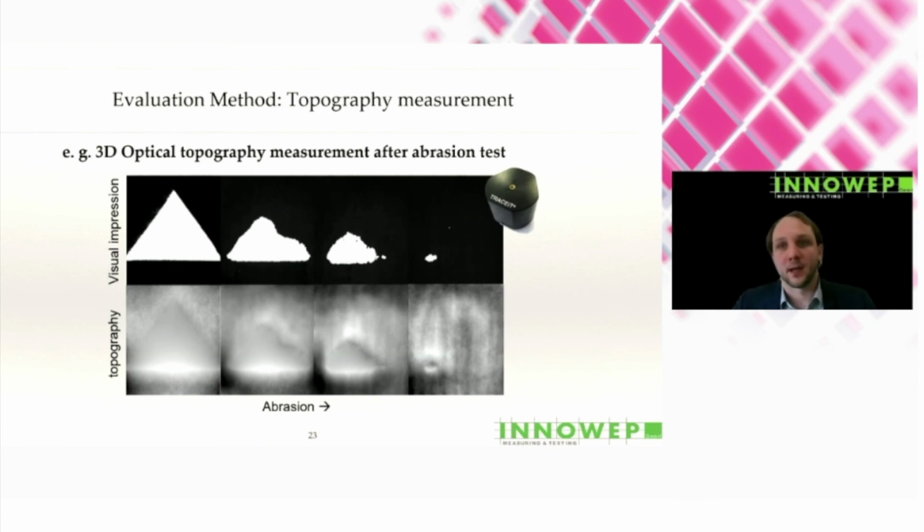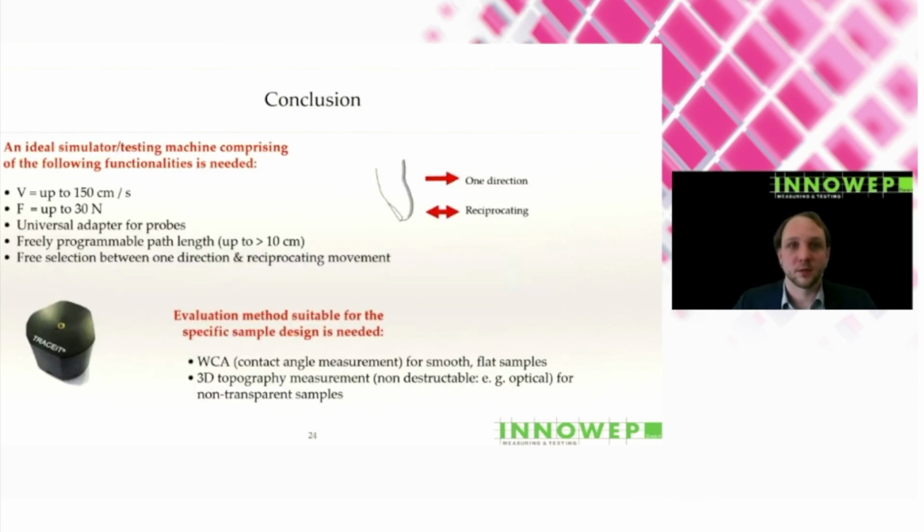Yeah, and I want to sum up and conclude that, of course, you have to make sure that the designed test pattern on one hand is suitable to match the real-life scenario. It should fit the right speed. It should fit the right movement type. It should fit the stroke length, load, and duration, of course, too.